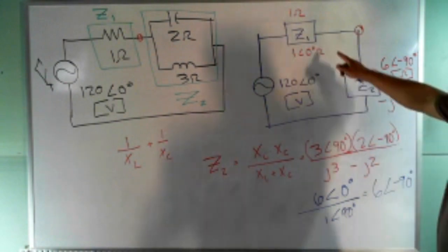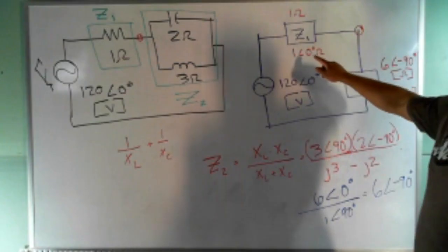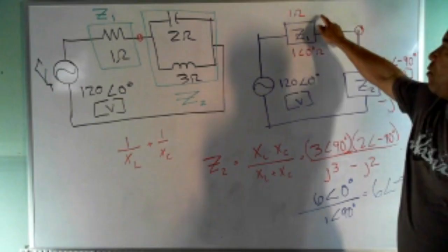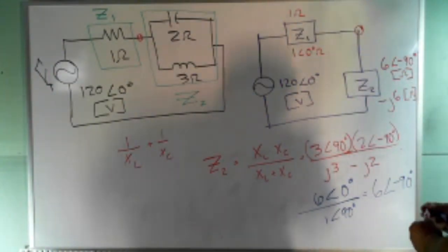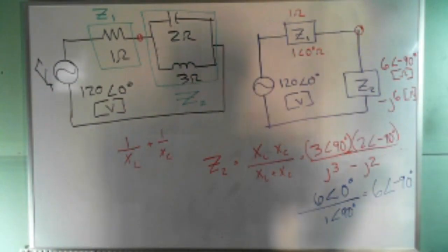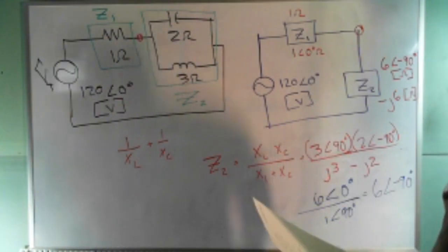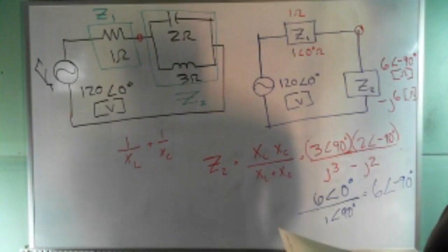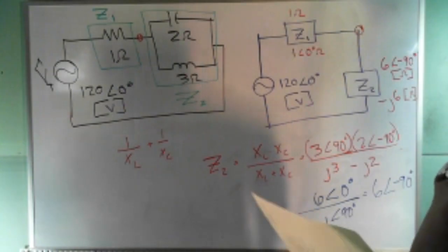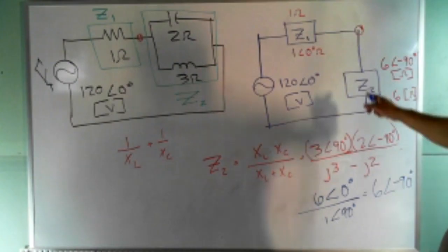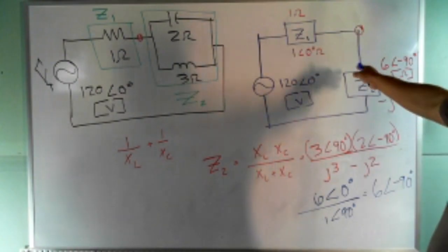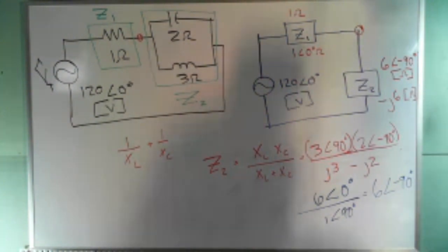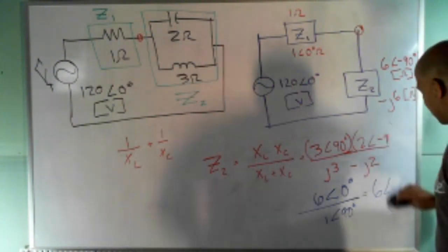So I got 2 block impedances. I'm showing the value of the opposition in both polar and rectangular form for all the block impedances. So under that part of the problem where he says first redraw the circuit using block impedances, that's what you do. That's number 1. But then number 2, find ZT in the simplified circuit. Well, that's easy because all I have is a series circuit over here. So I can find ZT all night long. I just add them up. So let's add these up.